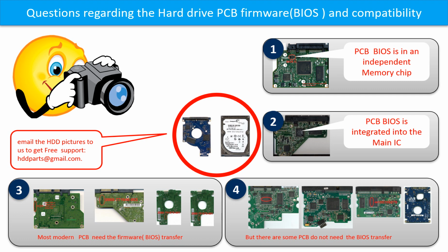Some PCB boards' BIOS are in the independent memory chip, like the first picture shows. Some PCB boards' BIOS are integrated into the main IC, like the second picture shows. Most of the modern hard drive PCB boards need to do the BIOS transfer before swapping the PCB board.